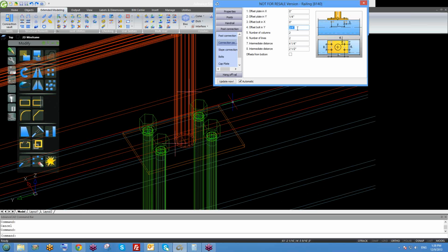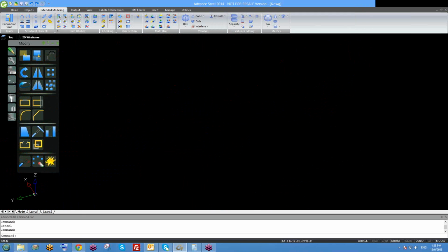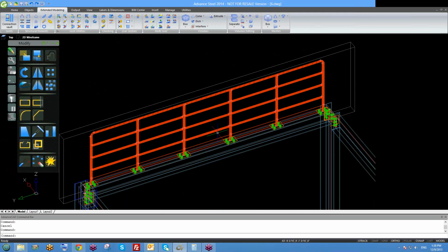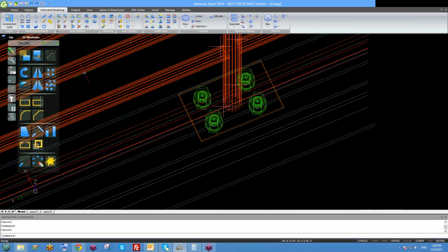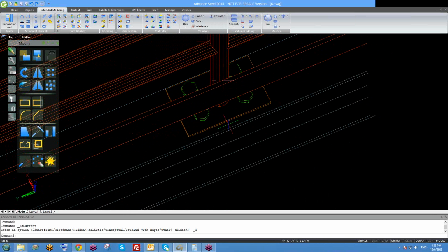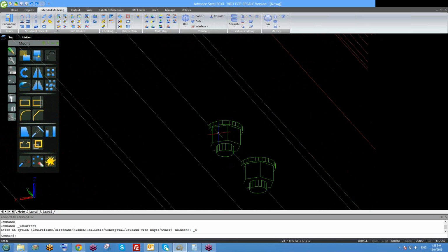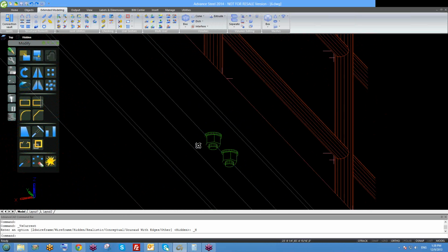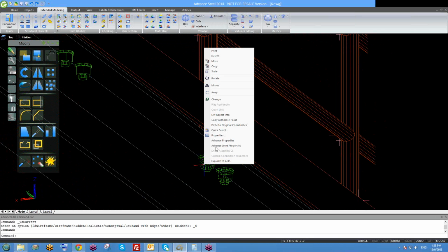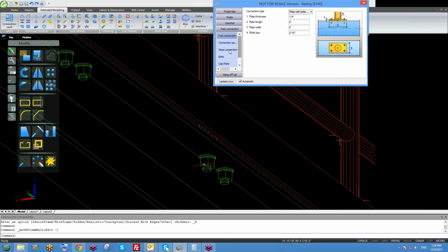How come mine does that when I put 2 for number of lines? I get a bolt all the way through both flanges. It's probably because you have a different beam. You can see here you should avoid this interfering between the bolts and the beam's web. So if you get that, it's going to create that odd connection for you.